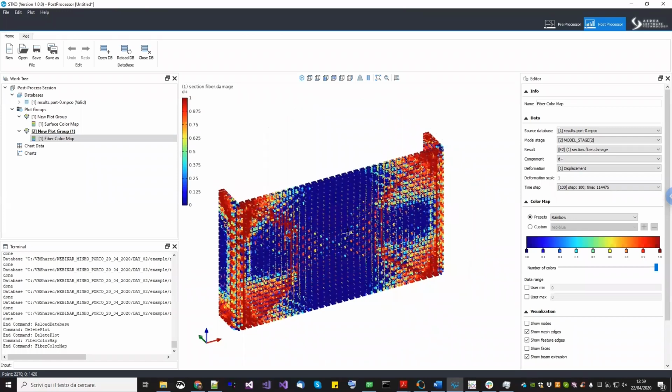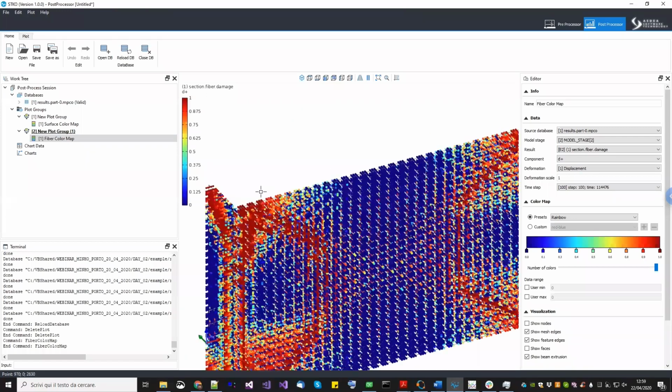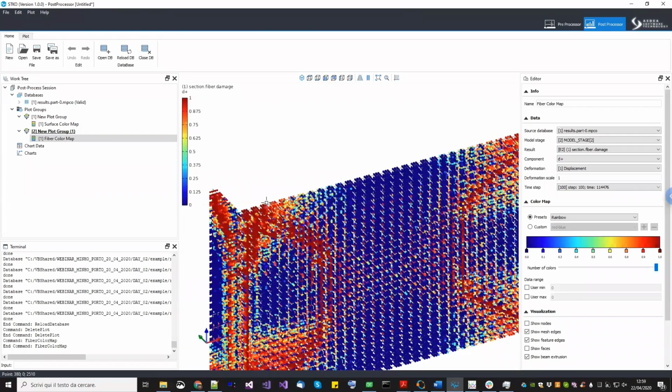So remember that if you are doing micromodeling, the typical size of this kind of wall is not the wall, it is the size of the mortar. So in any case, it will always be a thick plate theory, okay? You got another question? Okay, perfect.